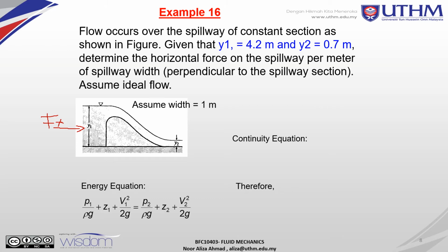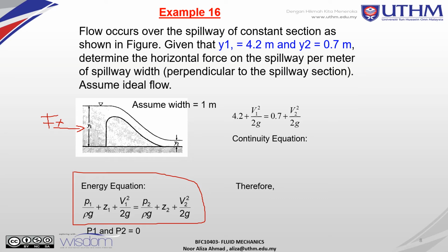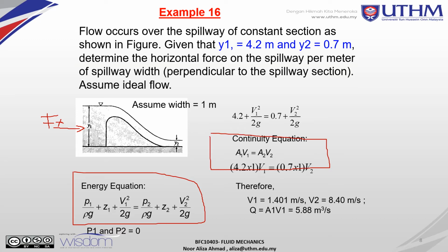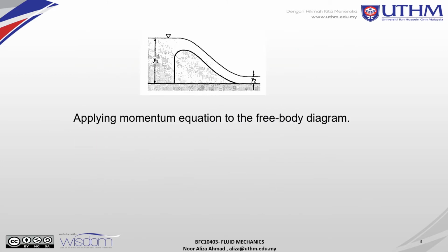First you must know the energy equation, the Bernoulli equation. And second, you must know the continuity equation, and find the values of V1, V2 and Q. After you get these values, you must apply the momentum equation to the free body diagram.